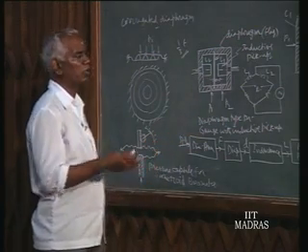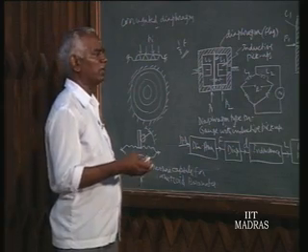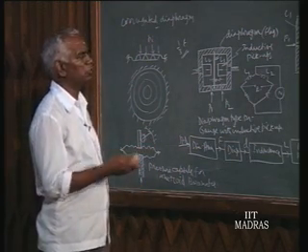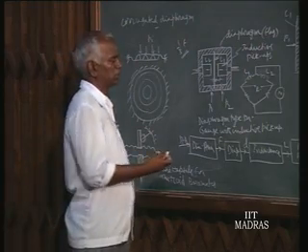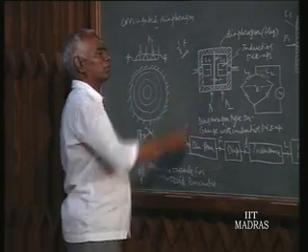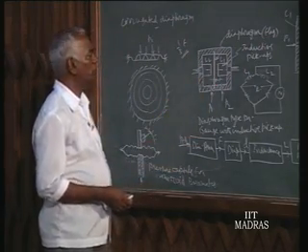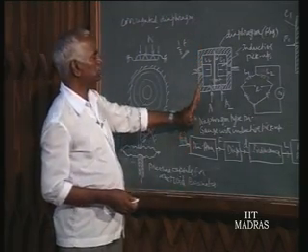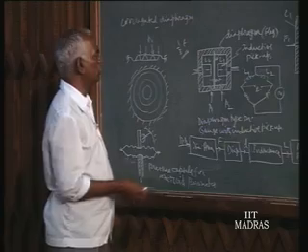We know that to convert a displacement or stress or strain, we can use the displacement of any member. We can use resistance or inductance or capacitance. How the inductance and capacitance are made use of in sensing the deflection of the diaphragm is illustrated in the following diagrams, figures.